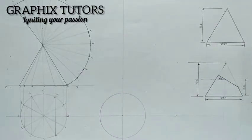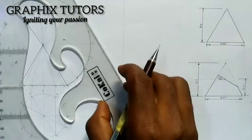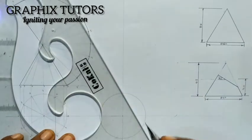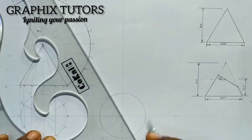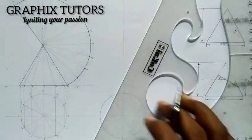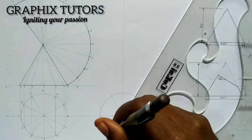And the same thing I did earlier, I'm going to divide it into 12 equal parts. This time I'll be using this, but it's the same procedure. You can use your compass to divide, or you can use your set square with the help of what? Your T-square.